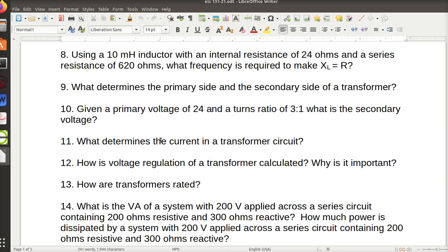As my resistance or my load varies between infinity and some minimal value that represents the full load, then my current will be in a range between the maximum that a transformer can handle down to 0. That's one of the interesting things about transformers. You think more load is more resistance. It actually works the other way. More load is less resistance.